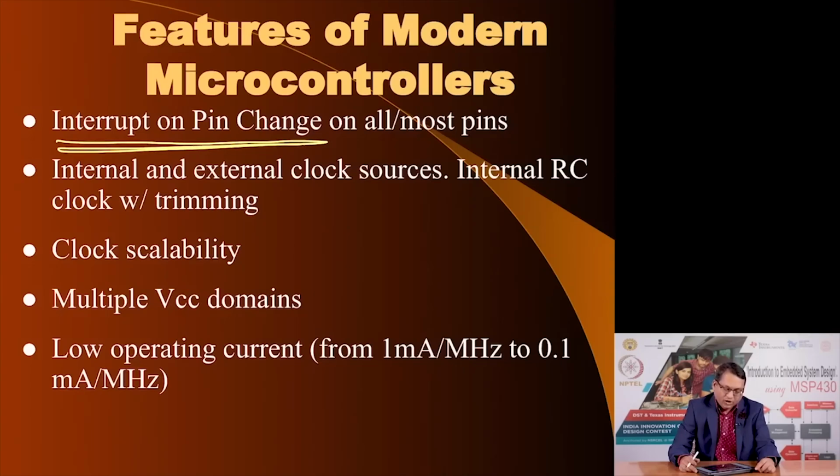Now, you need a clock to operate a microcontroller, and the reason is that a microcontroller, as an example of a logic circuit, is of the type what we call synchronous, a sequential synchronous circuit. So, for that you need a clock signal. So, you have to derive that clock signal in some way.